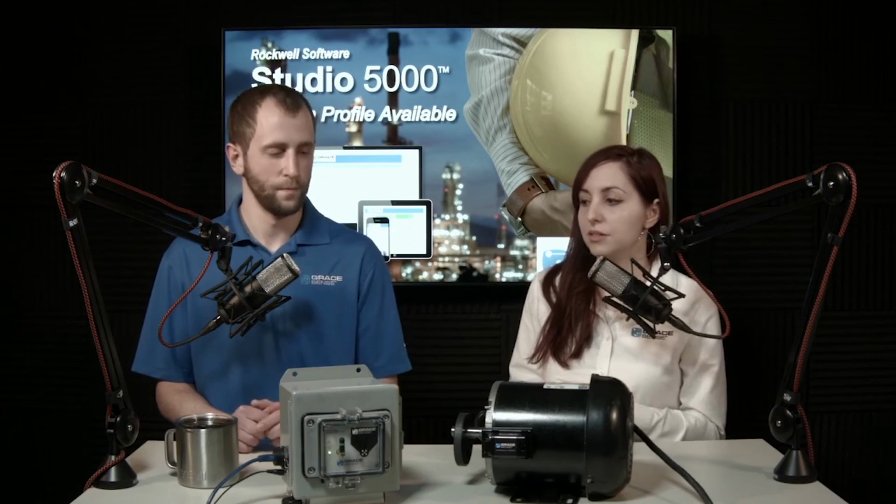But if your application is just monitoring the overall level, or you have a low frequency, low RPM motor, you would pick the VBT1. Otherwise, all of the settings are the same. The way you configure one or the other on the hub is exactly the same. Yep. Common applications are really getting into high harmonics with the VBT2, so you get early stage bearing wear. You get a little more time, a heads up that you're having some issues out in the harmonic realm.